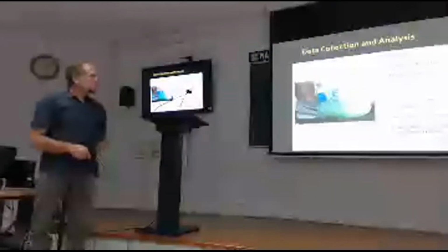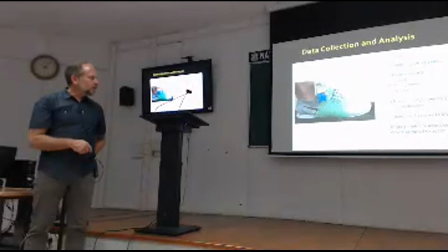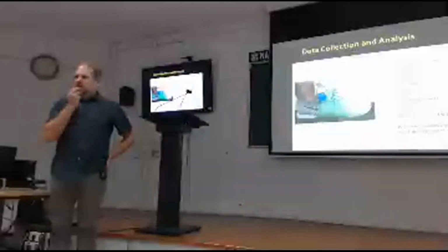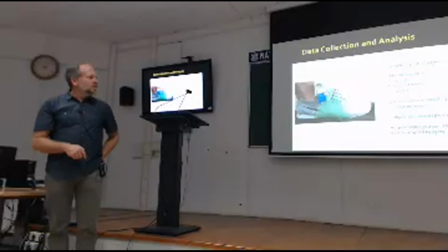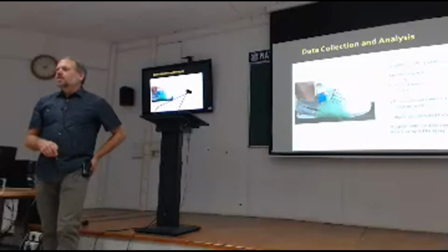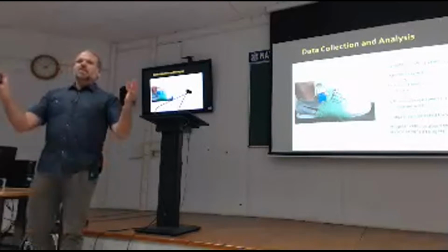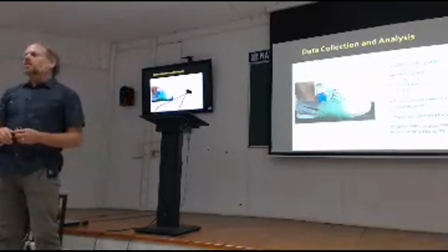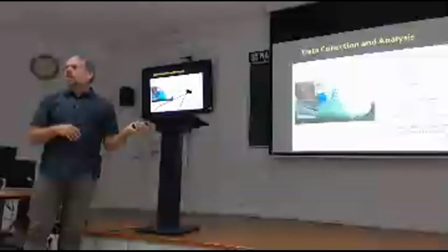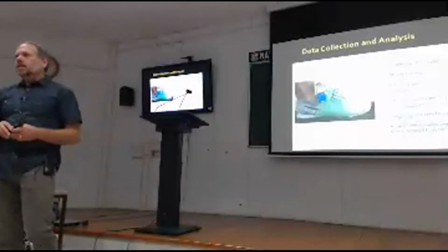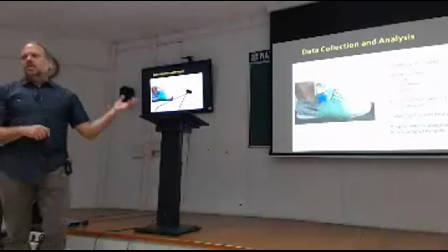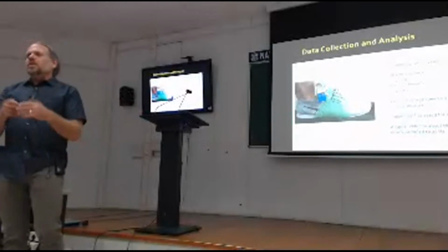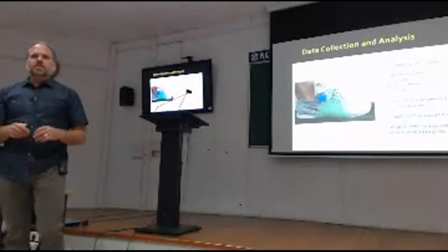So I was talking about what we get from the load sole, but from the IMU we end up only taking the angular velocity, that's the only channel, out of 9 channels. And this is chosen based on a sampling rate of 500. Most of the time we want to increase the data points we have for higher resolution, embed that in the shoe, embed that in the prosthesis. So right now we'd love to get all the data we can, but we're trying to find the minimum, which again is a unique challenge.